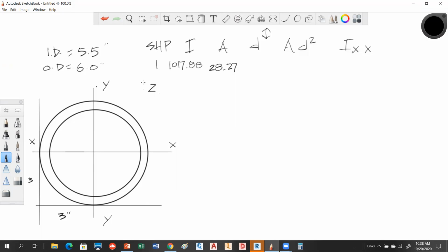Oh, you know what? What did I do? I did diameter. Sorry, my answer is wrong. Let me check something. So it's pi r to the 4th divided by 4. So that's going to be 3 instead of 4. I used 4, so I had a wrong value. Sorry about that. So my number was a lot greater than it should have been. How does 63.62 sound? Looks good. Okay, all right. I was using diameter before, so I was wrong by a huge factor.